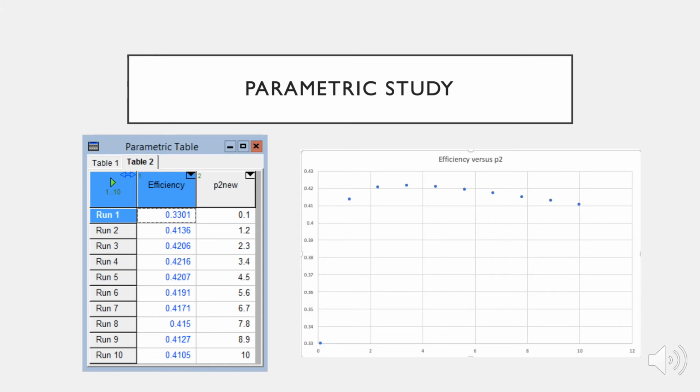An issue we came across when designing our Rankine cycle was deciding on the 3 pressures we wanted our isobars to be. We decided on our first pressure to be 40 bar because that would make the power plant supercritical. We also made our lower pressure 0.07 bar because that was close to the minimum pressure that we were allowed of 0.06 bar. The problem then became what we should choose for our middle isobar, because when we decided to guess and check a bunch of values, it seemed to affect our efficiency very much, so we wanted to nail it down as best as we could.